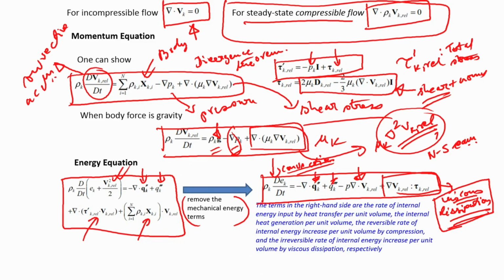So, why is viscous dissipation important? This is basically the work done by the shear stress, correct. The work done by the shear stress is a lot higher when these two fingers, which, in the analogy of two parallel plates, are like two parallel plates. Naturally, the heat generated when the flow goes through these two fingers of mine is a lot. But when I spread the fingers out, the shear stress is very low. So, viscous dissipation is important, especially if you have a very high velocity flow going through a constrained space.